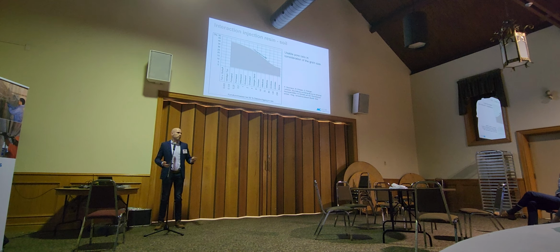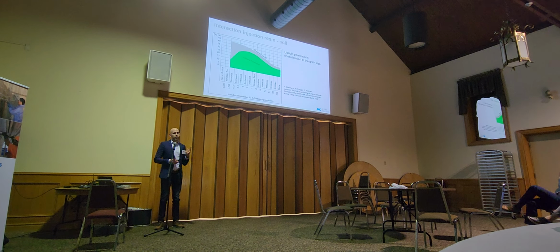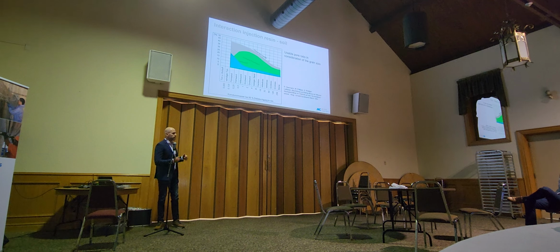About sandy soil, let's say 30%, 32% of porosity, but I still have something inside, and therefore I only have part of it as a usable pore ratio. Why? Because I will never, with any injection, either if I use polymer or cement, either if I use water, fill 100% of the pores. There is always some water which is bonded to the solids.